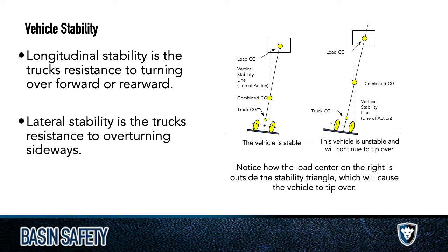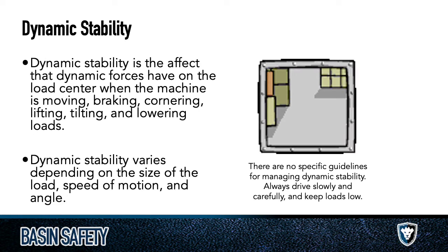So as you have a load on the equipment and you lift it up, the center of gravity will change. It will rise with your load. And so when you're traveling, especially because the center of gravity has changed from the base of that equipment, which is where it is when the load or the forks are completely down at the ground, as you lift that load up and start to move, or even as you're holding the load, the center of gravity will change. It will change with the position of that load. When you go to move, that is considered your dynamic stability.